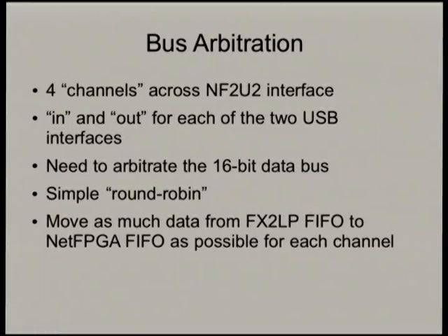So my Verilog code, after it's got the clock right, the next thing it has to do is arbitrate between the 4 data sources, the 2 inputs and 2 outputs that are on those two USB interfaces, and multiplex all that data into this 64-bit data path. And again, it's going to add the 2-byte padding to the front, so that as the packets come in off USB and hit the NetFPGA switch reference framework, they'll all be lined up nicely. Using a round-robin scheduler, so it just looks through which FIFO is ready to do something, and then moves all the data out of that. So there'd be a little bit of latency there, but not too much. I have it all modelled somewhere.